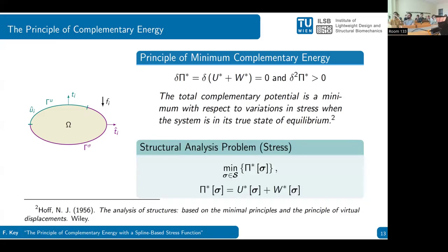Then the structural analysis problem, formulated in stress, can be written as, okay, we minimize this total complementary energy, which is now a functional of the stress field, where all the stress fields are statically admissible, denoted by this category S, where this function is just given through these two contributions, internal and external. Okay.